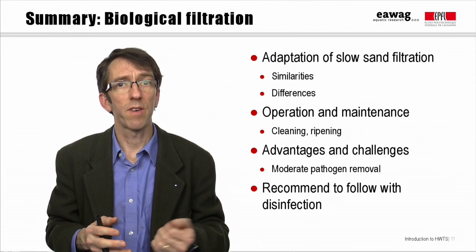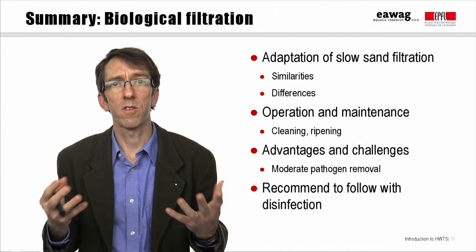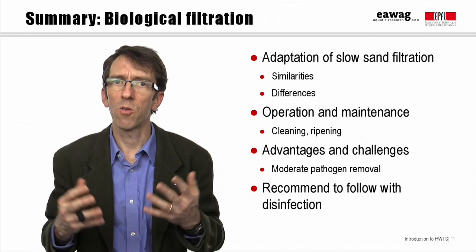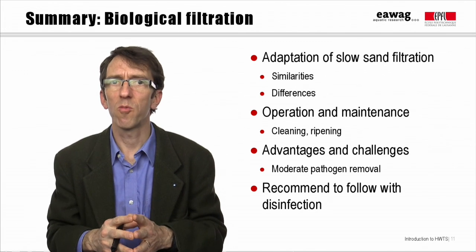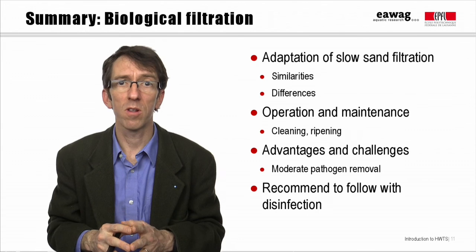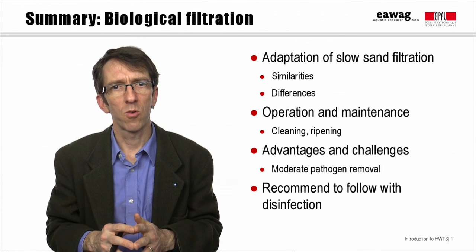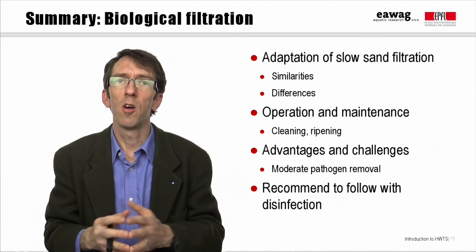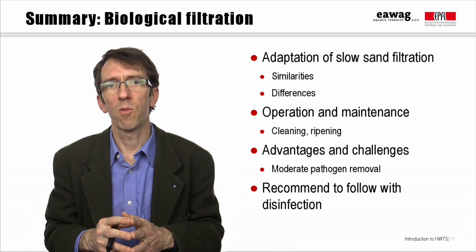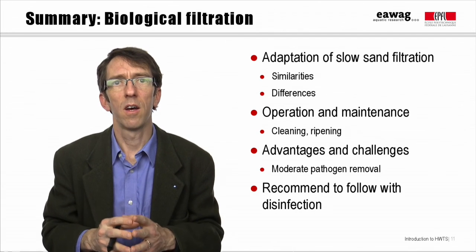We've gone over some of the advantages and challenges for biosand filters, and one of the significant challenges is definitely only moderate pathogen removal, 1 or 2 log removal for bacteria, less than 1 log removal typically for viruses. So it's best to think of biosand filtration as a filtration technology, but not a disinfection one, and one that should always be followed with safe storage and ideally disinfection.